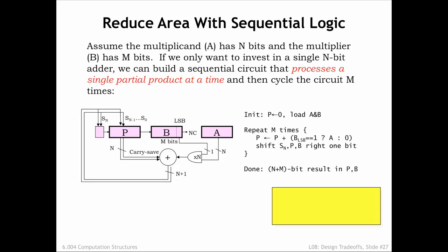The value in the P register and the output of the adder are in carry-save format. This means there are 32 data bits, but in addition, 31 saved carries to be added to the appropriate column in the next cycle. The output of the carry-save adder is saved in the P register. Then, in preparation for the next step, both the P and B registers are shifted right 1 bit.